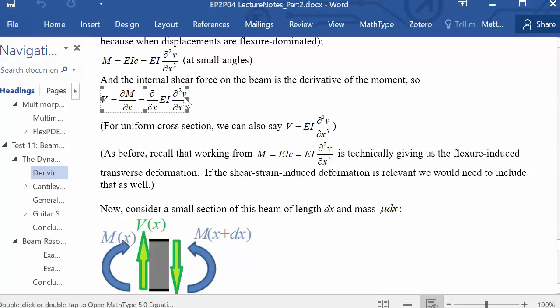And as long as the moment is responsible for all of the displacement, then we can call this just the entire displacement, rather than saying that this is the displacement due to bending moment only. And again, as long as it's mostly small displacement, you can say that that is just in the y direction if we have a beam that is long in the x direction.